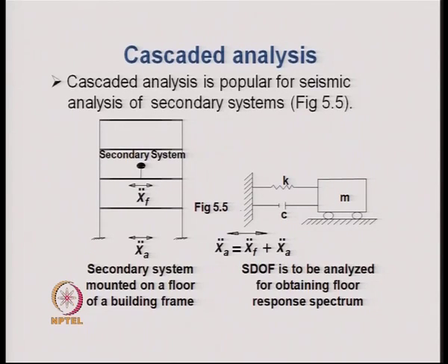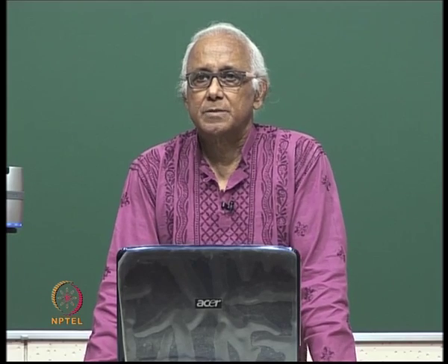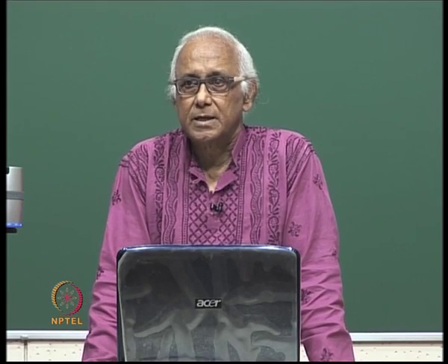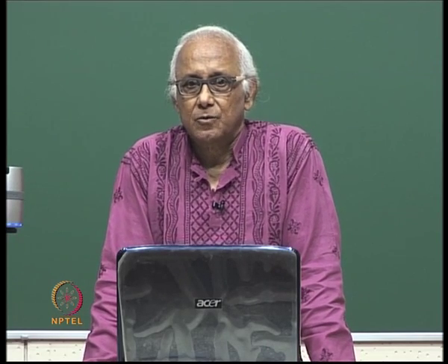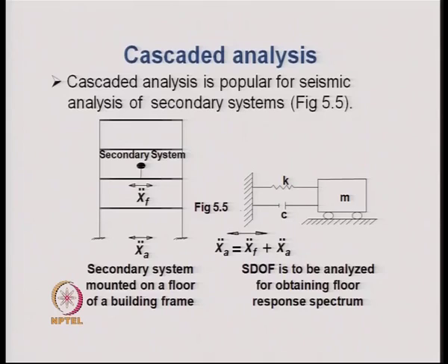Today's lecture will concentrate on the cascaded analysis, the use of the response spectrum method of analysis for non-classically damped systems. Cascaded analysis is very popular for seismic analysis of secondary systems. In fact, the cascaded analysis was specifically designed for the earthquake analysis of secondary systems which are there in many structures.